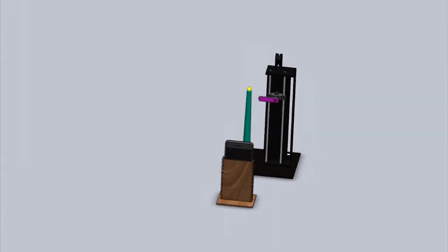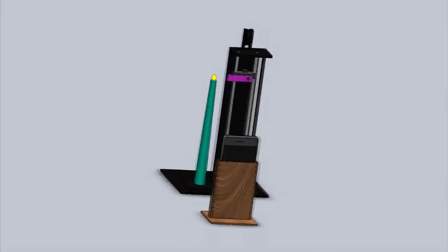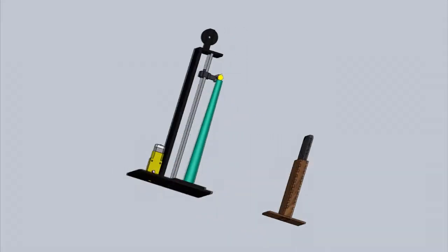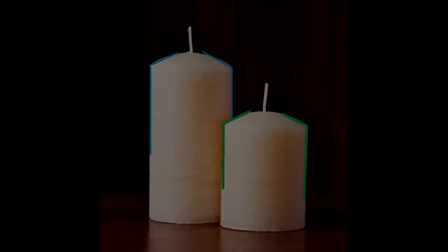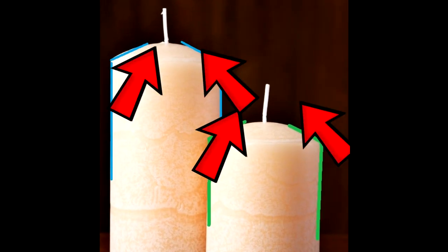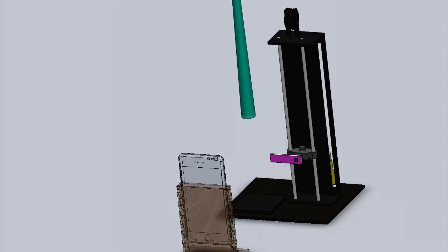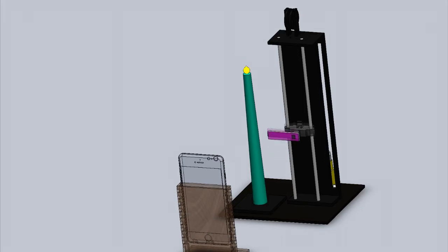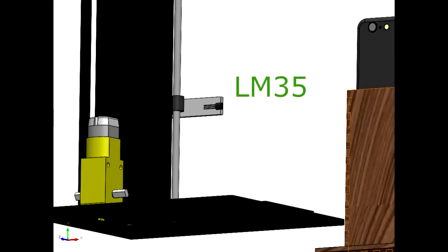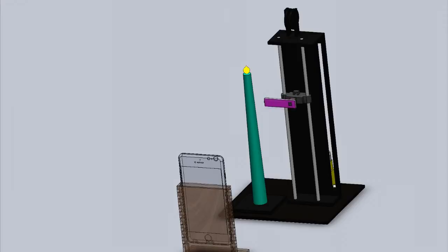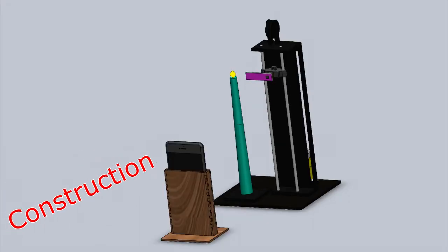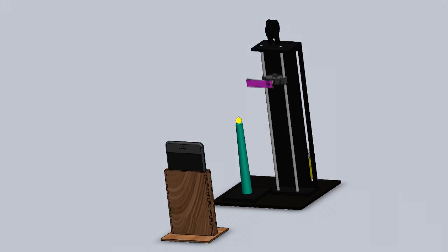The present project consists of a mechatronic system that monitors candles, focusing on the length of the flame when there is a change in the cross-section. The system consists of a structure where in the central part of the base the candle is located. Similar to an elevator, the cabin that contains the temperature sensor LM35 will be located at the same level of the flame. While the candle height decreases, the cabin will go down automatically and thus measure a uniform and approximate temperature of the flame.